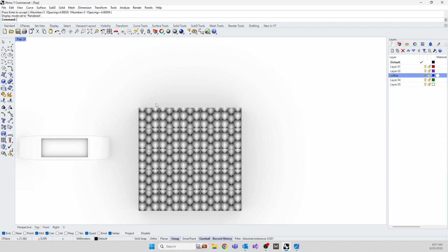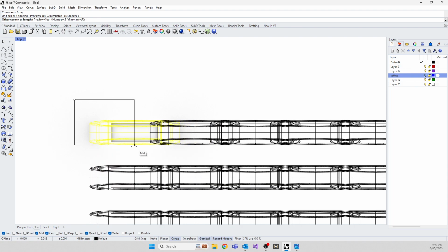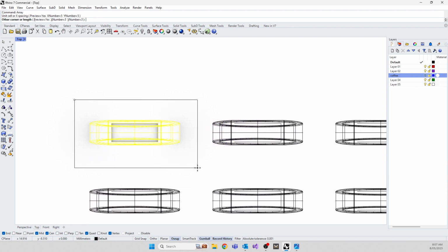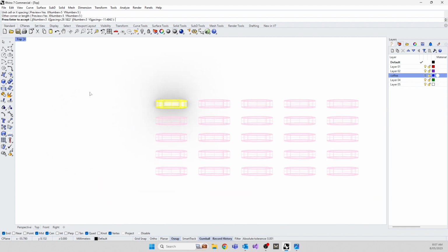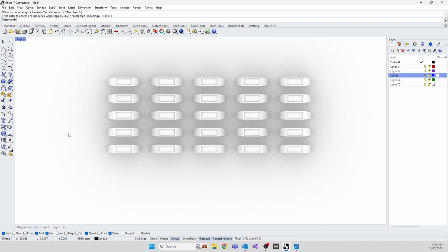You can pull out 25 by 25 by 25. Same thing, you can do it with a ring. Array. And I'm going to keep it in X, keep it in Y, and keep it over there. What's my cell spacing? I want to make 25 rings like this. Isn't that a lot easier than copying? Okay, so we've gone through how to bring in meshes.